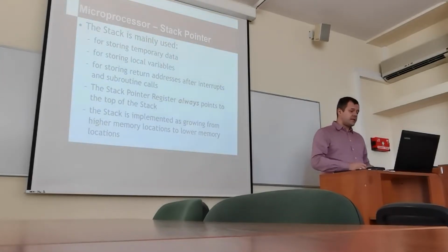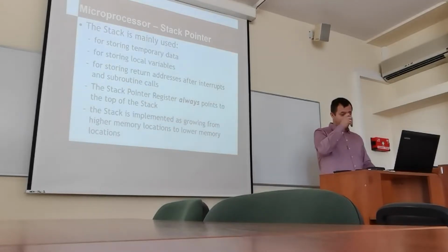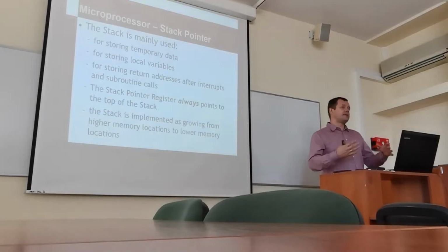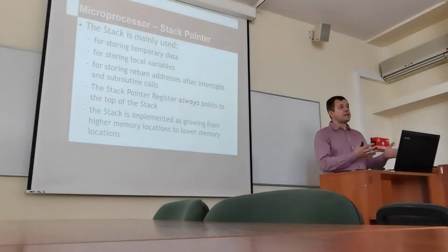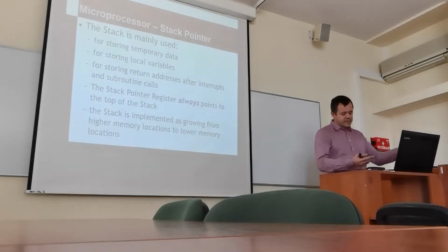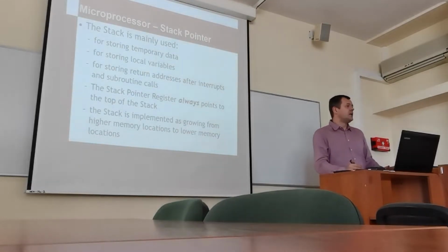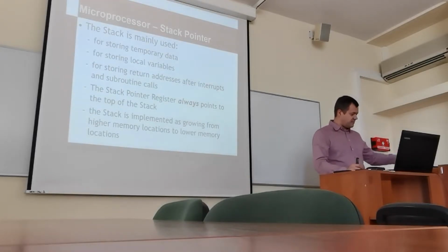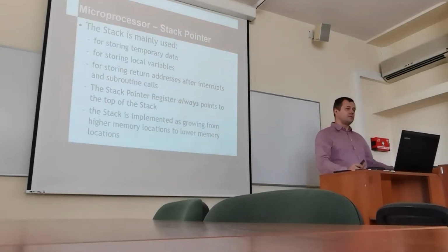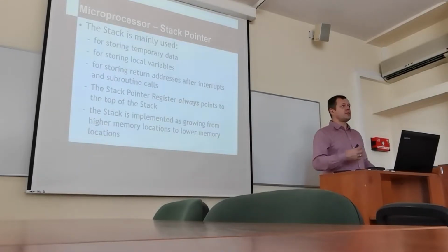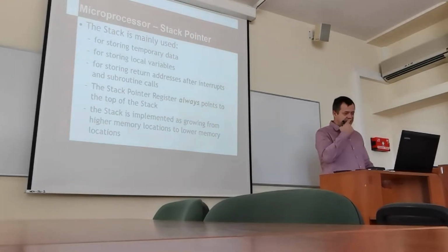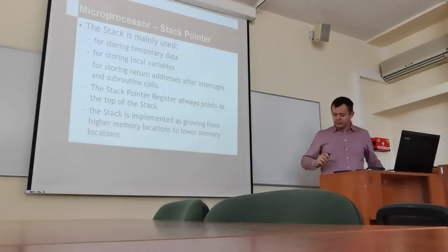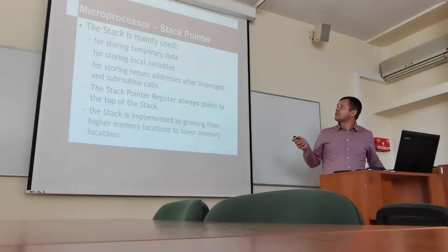It's a stack pointer, part of a microprocessor. And we always need to store temporary data somewhere during calculation. So, from a practical point of view, quite often whatever we count, we need to put it somewhere to the side, then return back to this later. And this is so frequent, so often, that this mechanism was made available in the microcontrollers today.